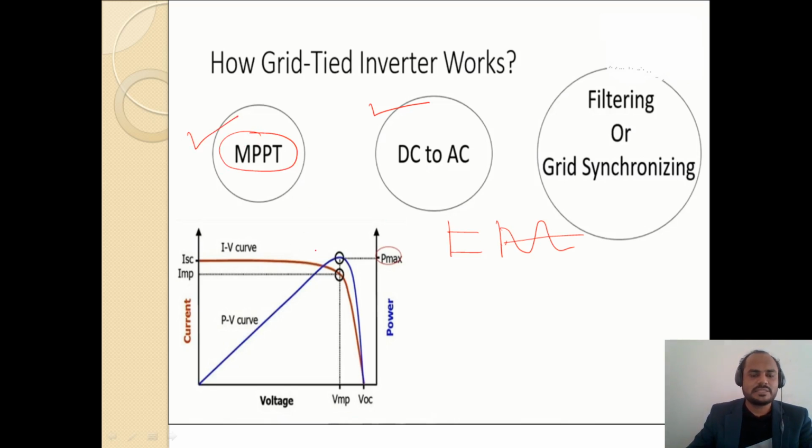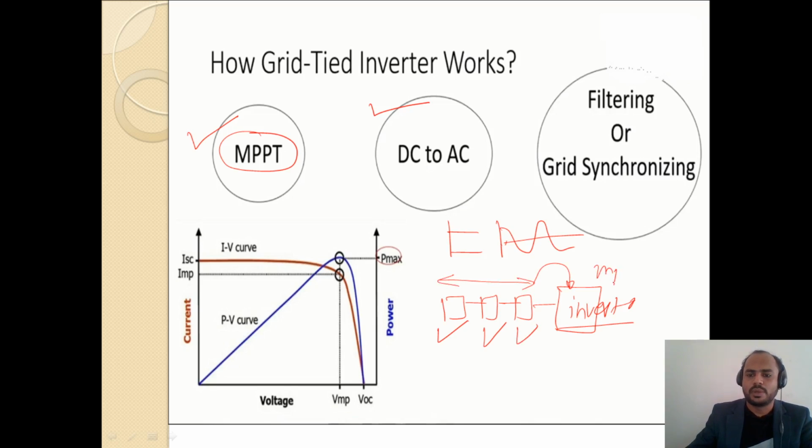So basically the maximum power point tracking is nothing but, let's say we are connecting these 3 solar panels in string combination or series combination to this particular string inverter. If we want to extract the maximum amount of power from these 3 solar panels that we are connecting in series combination, we have to give the output to MPPT number 1.